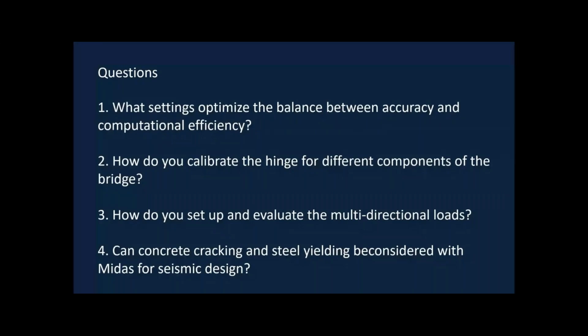Coming to the fourth question, can concrete cracking and steel yielding be considered with MIDAS for seismic design? Concrete cracking and steel yielding can be considered, but they cannot be represented by the plastic hinges that we have considered right now.